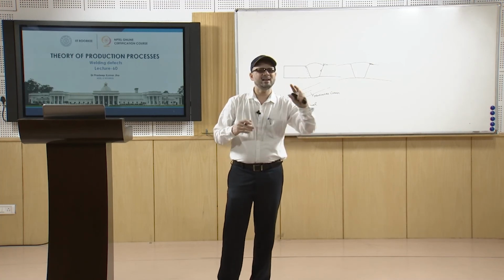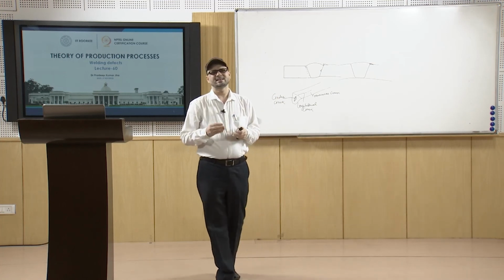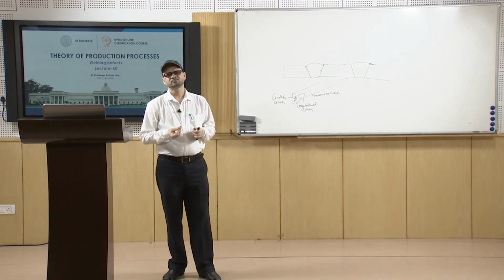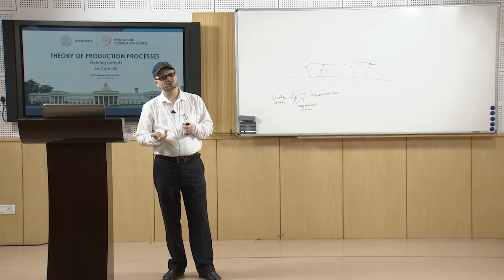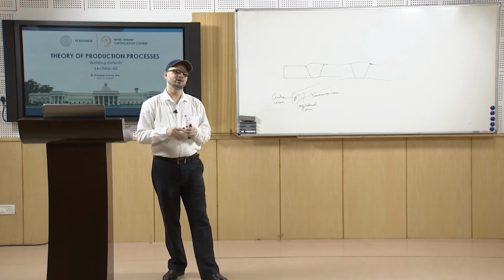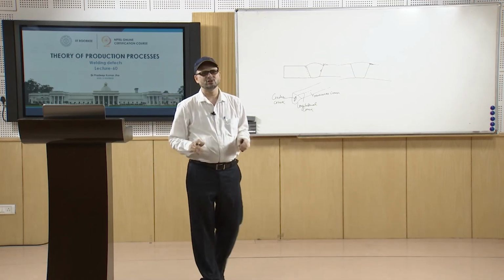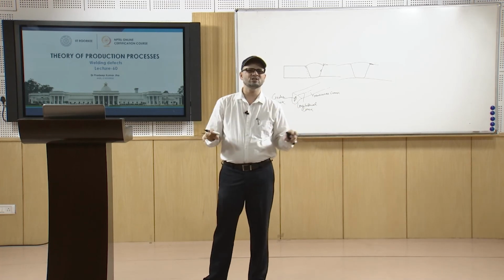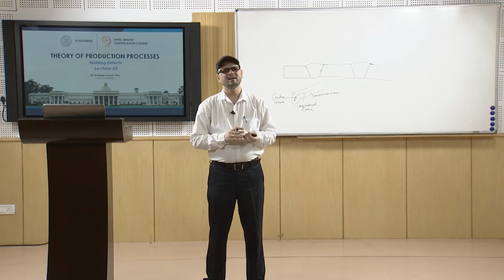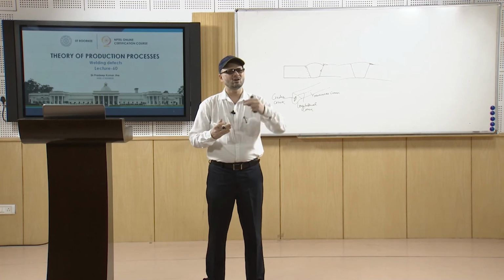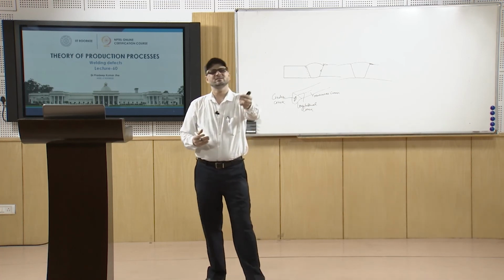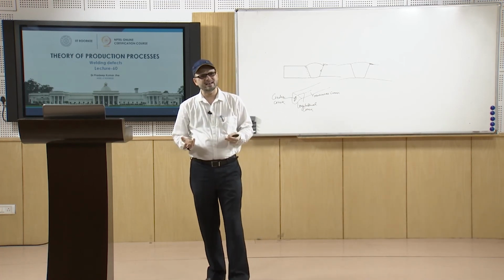Mainly what you see is the selection of proper welding parameters, proper preheat or post heat, and proper preparation of the joints. These are the main things on which you have to work, and then you can see that if the stresses generated are less, then the chances of cracks will be less.